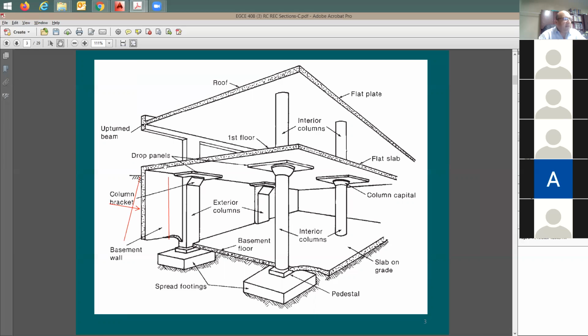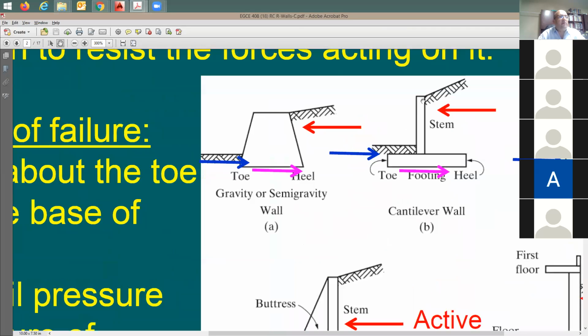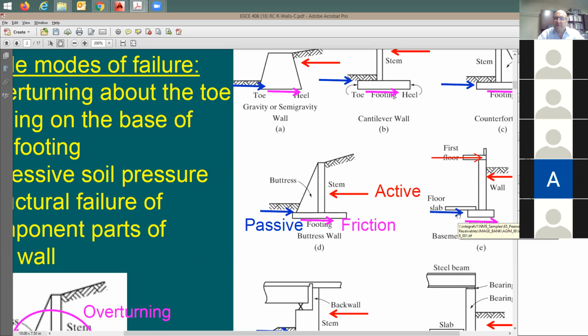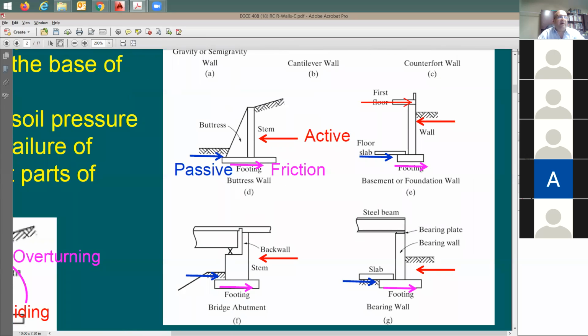This is called a retaining wall, but this retaining wall, the structural system, is going to be like a simply supported beam, right? At the top, you're going to have the first floor resisting the movement, and at the bottom, you're going to have the foundation and the concrete slab on grade to resist it. Now, I want to compare it to this retaining wall. There is nothing here to restrain the top of the wall. So the pressure comes from this side, and this works as a cantilever system. This one here has a support at the top and also a support at the bottom, so it is like a simply supported beam, and the force is coming from outside. You should be able to model the stress coming from the soil like this.